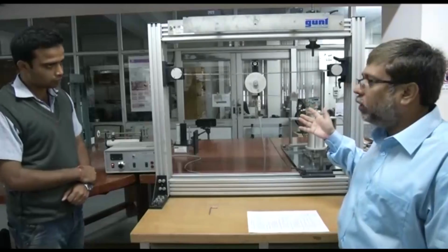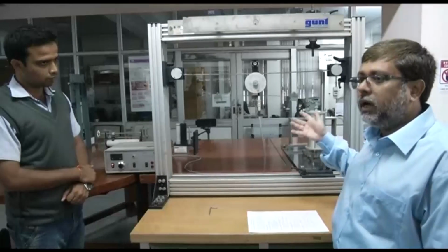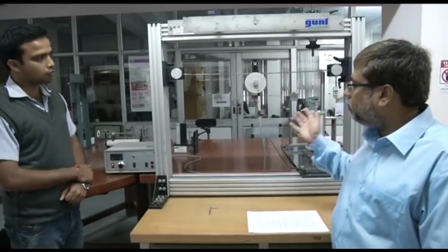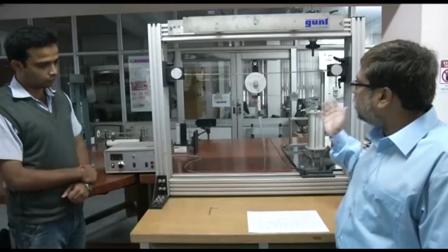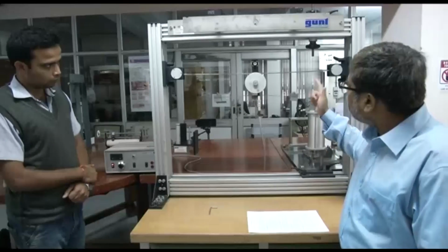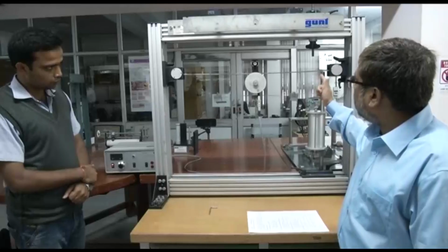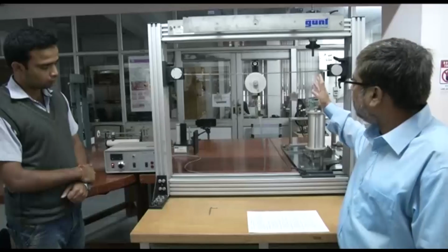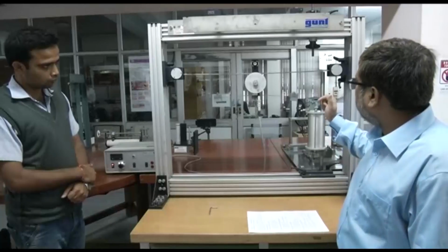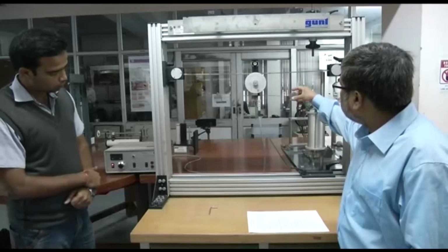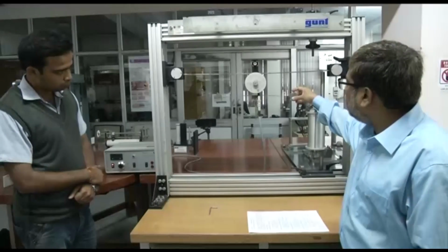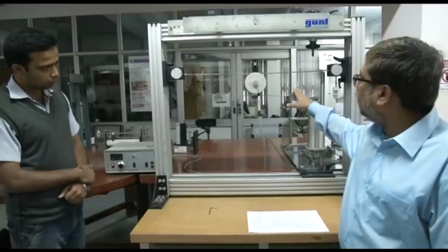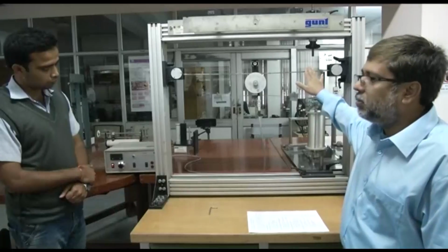Very similarly, we will also see that this happens in practice in various other types of structures, like power transmission cables or machines, etc. Now, we will first show how this excitation is affecting the performance of the beam, how the resonance is happening, and then we will show that once we attach this special system to it, which is called a tuned mass damper, we can control this excitation, we can control the response of this system and bring it down.